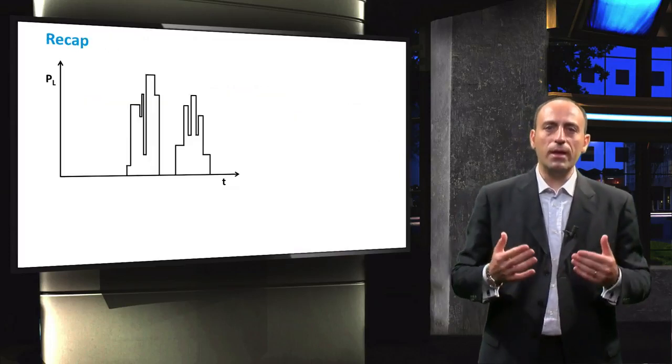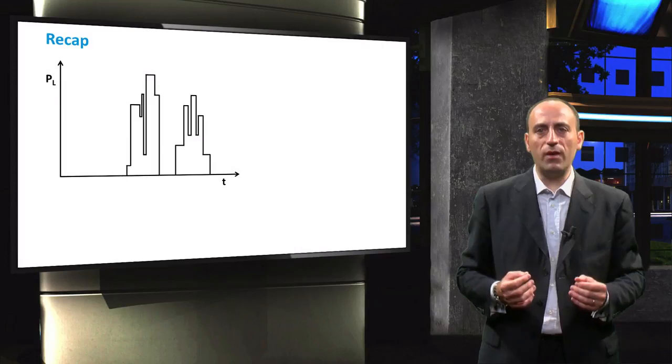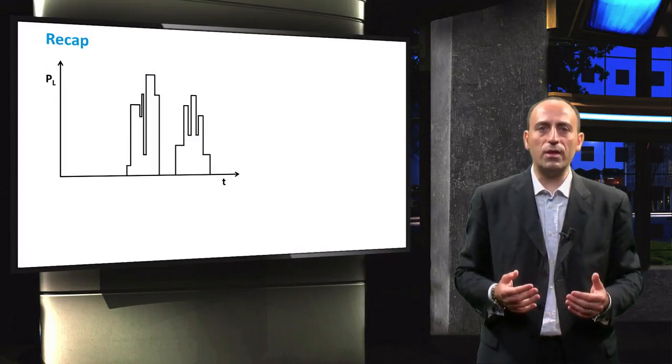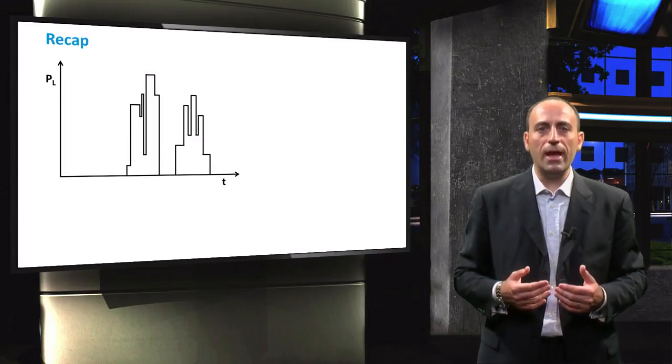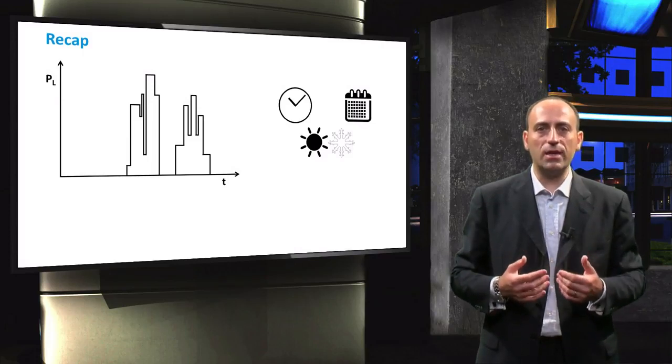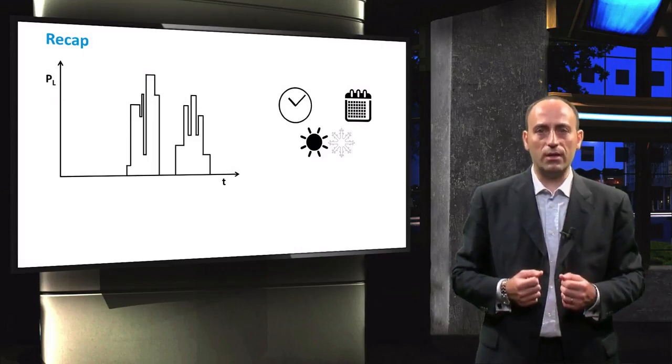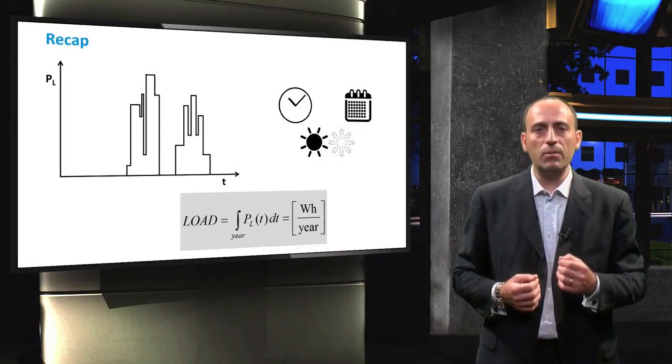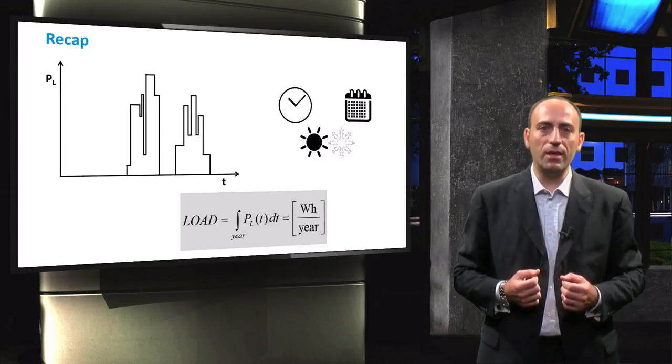To conclude, in this video we discussed the load profiles and learned how to use these profiles to analyze the load demand, and we also considered the daily, weekly, and seasonal timescales that can be used for load analysis. Finally, we determined the total annual energy demand of our loads connected to a PV system.